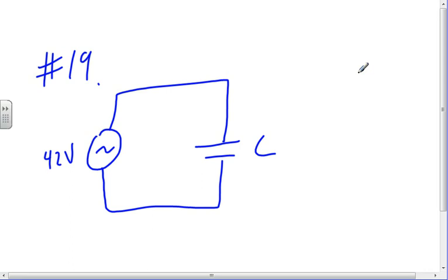In fact, we were fixing a TV set last spring, and we didn't have the right size. We had the right size capacitor for capacitance, but not for voltage. And I ordered the right ones, and some of my glorious students decided to go scrounge through the parts, and they found a different one. Instead of the 250 volts, 450 microfarads I needed, they found some 100-volt ones that were the same 450 microfarads, and they wanted to know if they could put them in. And I said, sure, why not? Yeah, no sweat.